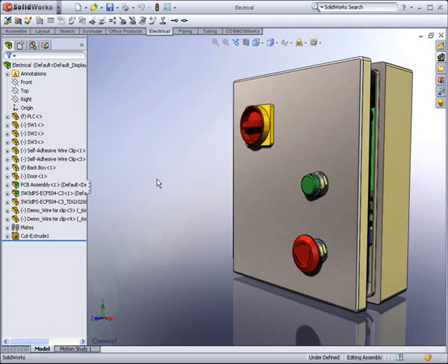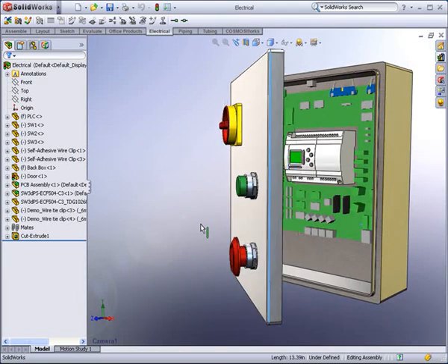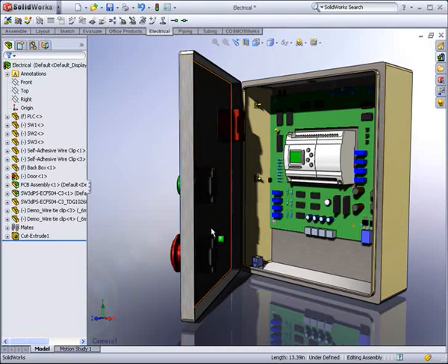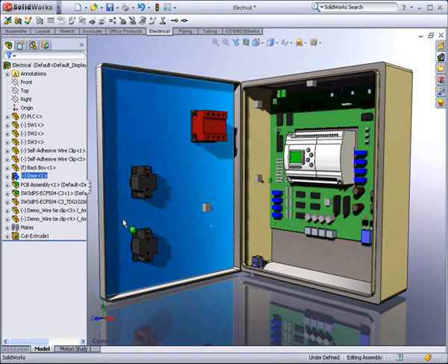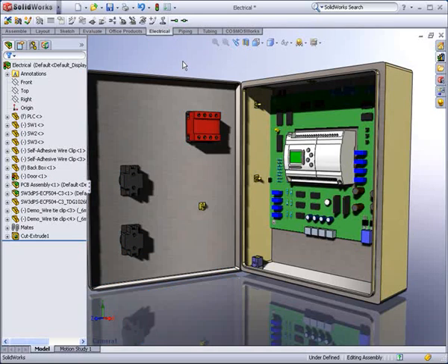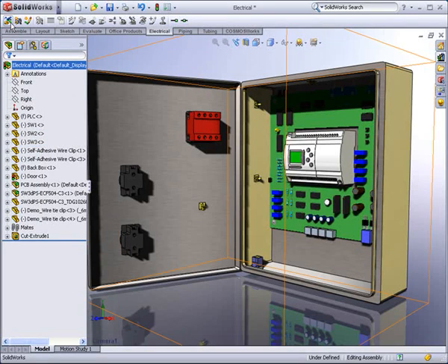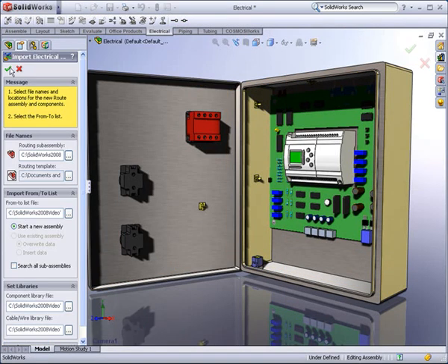SolidWorks electrical routing streamlines the routing workflow. For example, SolidWorks provides auto-routing of wires using your existing from-to wire list, which can be read into SolidWorks. Then SolidWorks will look for components with the same name as the components found on the schematic. SolidWorks recognizes single and multi-pin connections and automatically develops connections, so wiring is fast and accurate.